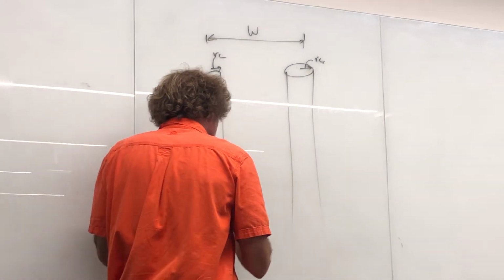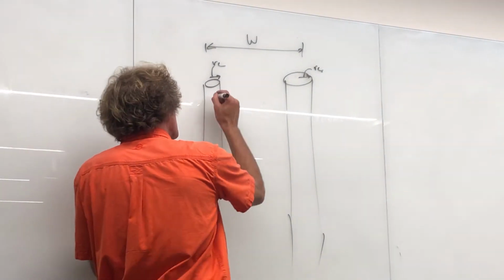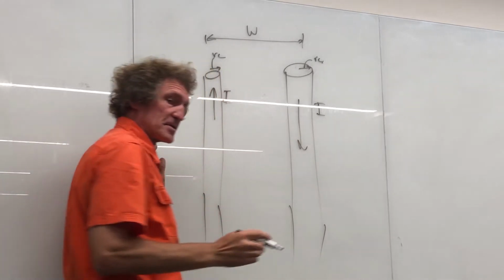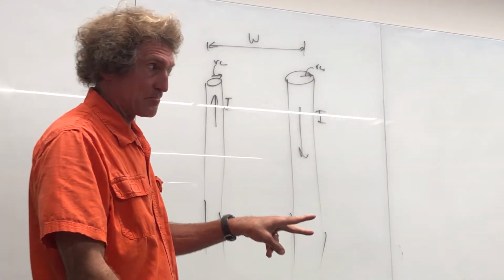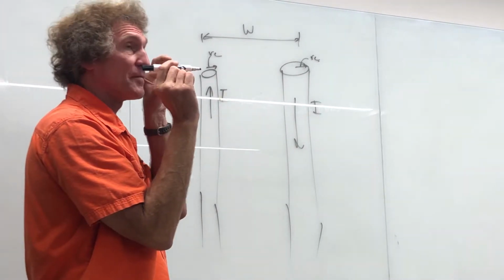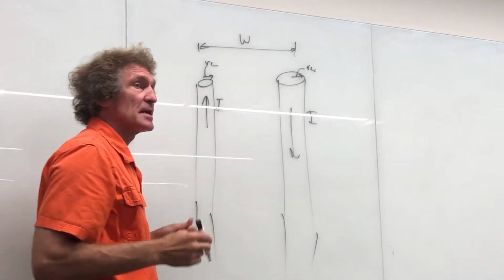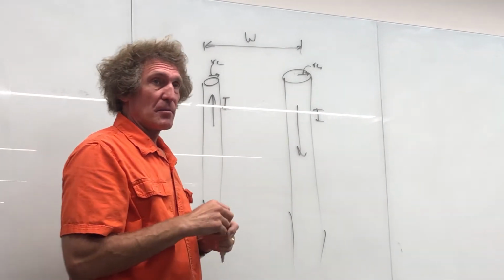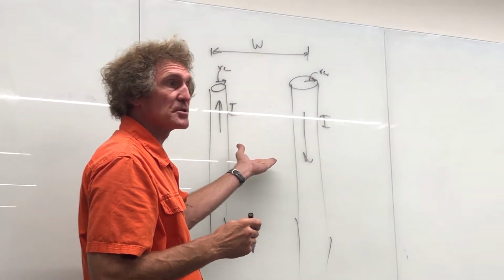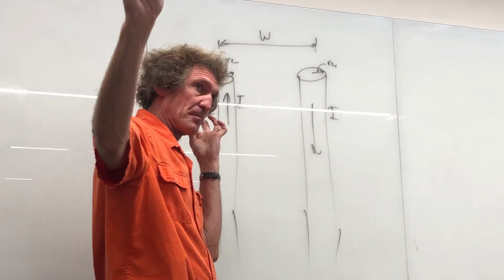Now, here's the assumption here. You got to understand this. We're assuming that this works in a differential mode. In other words, current flows this way and current flows this way, same current. Think of an extension cord plugged into a wall, right? Current comes down one wire and goes back through the other wire, right? It's called a differential current. If they were in the same direction, that's called a common mode current, right? But this is differential, and this is the way typically most extension cords and systems are used. Power lines have this, all right? They have current going down one line, coming back through another.